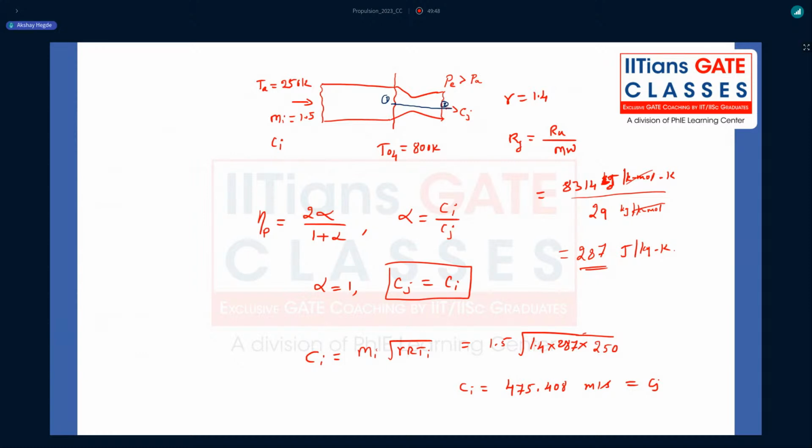In this condition, what happens? You will find expansion waves, right? Expansion fan. Because still you have to reduce the pressure. That can happen through expansion waves. So that means as long as the nozzle is not at fully optimal condition, I don't get maximum thrust. If I want to get maximum thrust, then I have to reach towards the optimum expansion condition.